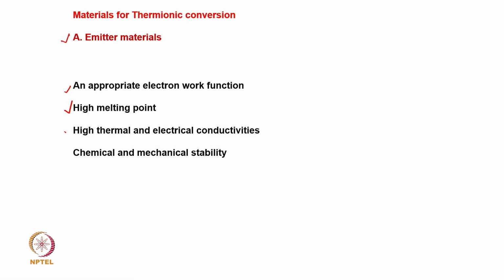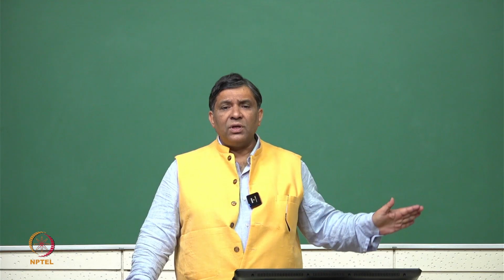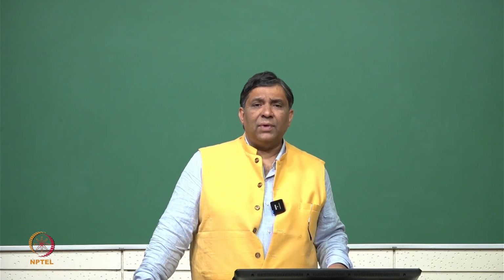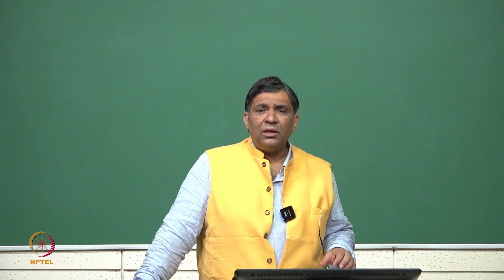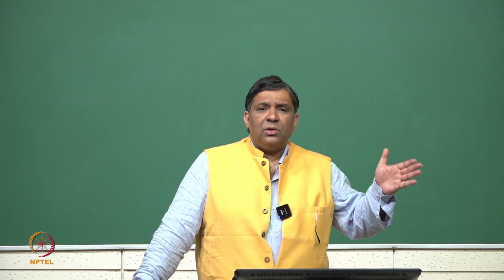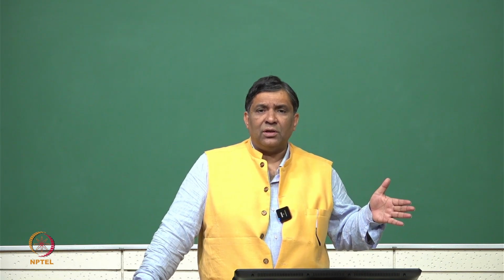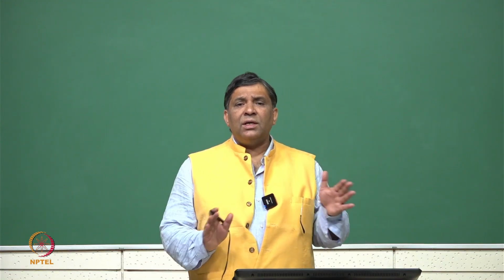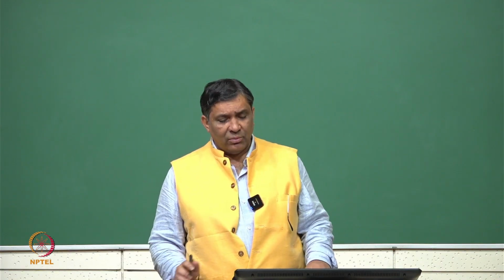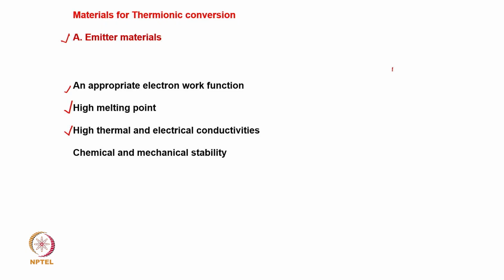High thermal and electrical conductivity. It is a very important point, because we are heating the emitter material, okay, at a particular location of the material. So, heat has to be conducted throughout this emitter material.